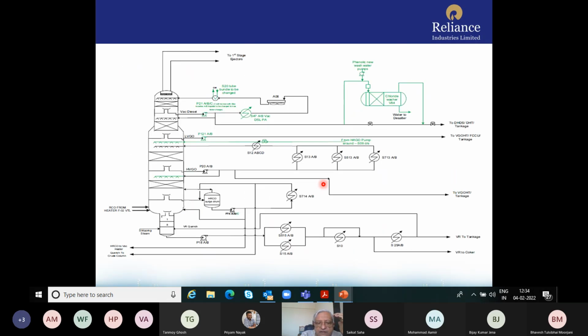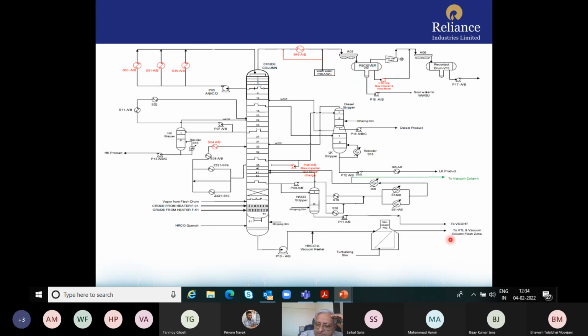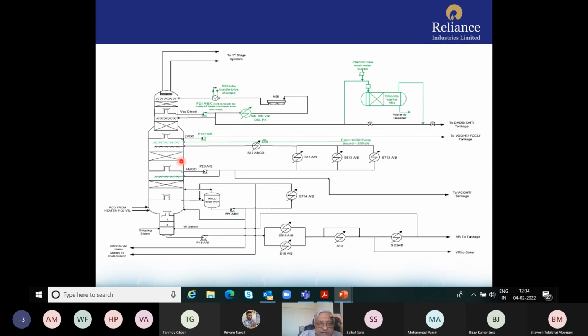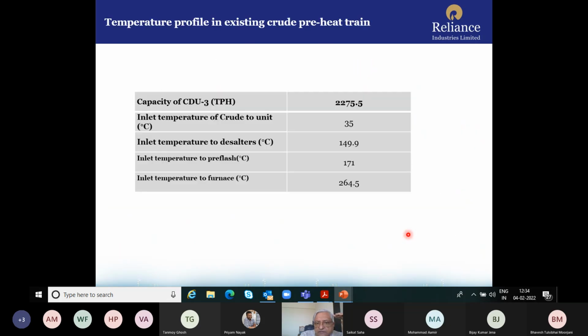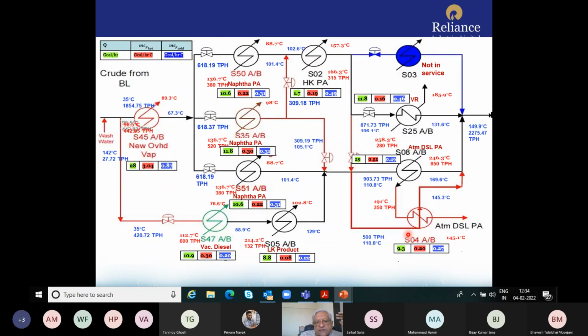So this is just to give you a complete perspective. And the same refinery has this vacuum tower also. This feed coming from the bottom is taken to the vacuum tower, and here we have the same. Only here there's a diesel also being withdrawn, and so you have again steam jet ejectors etc. here. And this is the LVGO, this is the HVGO, and vacuum residue. And this is just to give you an idea.